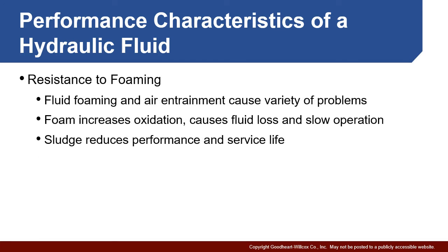Now, a common problem with any type of mixing of fluids is foaming. The big issue, of course, with foaming is that it traps air in air bubbles. This is referred to as entrained air. We want to make sure that we don't pull that air into the piece of equipment. We talked about that a little bit with pumps, issues of contamination, but also major concerns with cavitation.